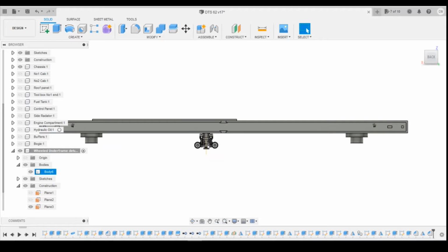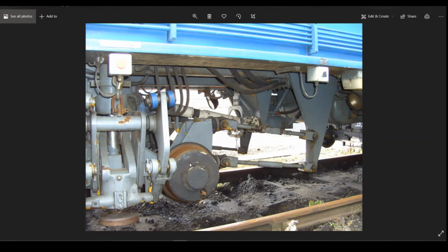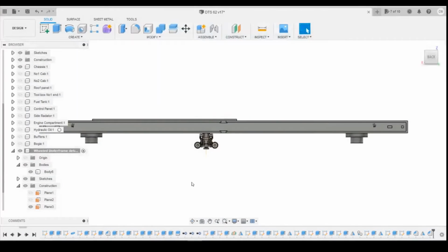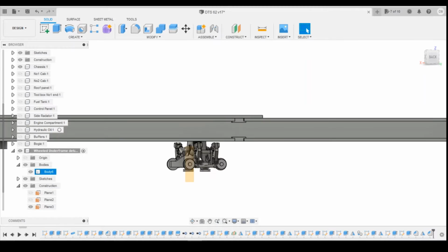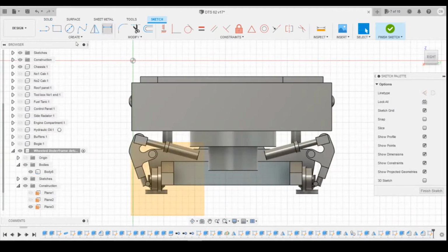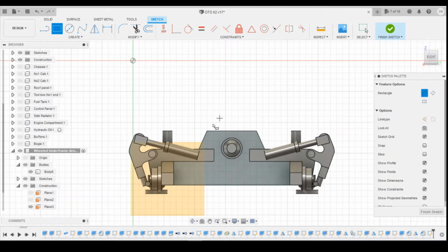So we're drawing the one that's to the left of that cutout. So we're drawing this unit. So we need to draw on this end up here, not that end. We're going to copy that across. So what could we do? So let's have a think. If we draw on the front surface of the unit there, turn the chassis off. Let's draw a rectangle. We're going to go all the way across both sides there. It's going to be 4 millimeters across, and let's go 0.5 so we don't interfere with the circle part of the drivetrain here.